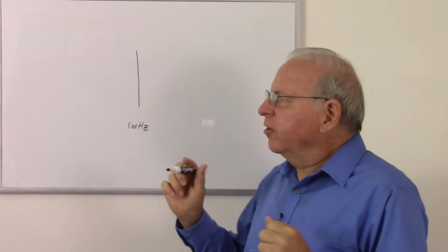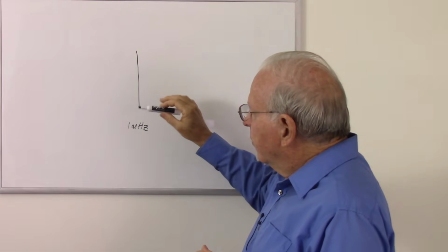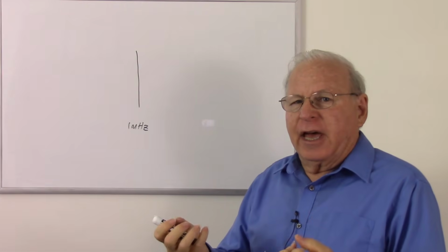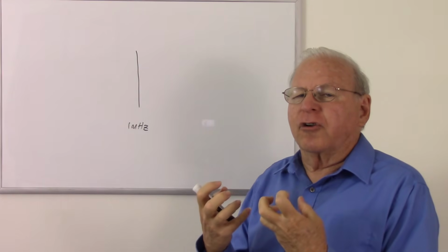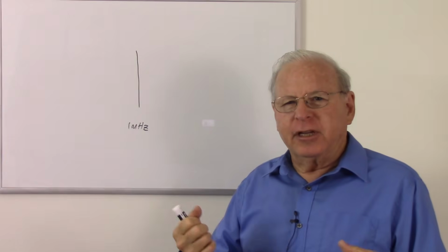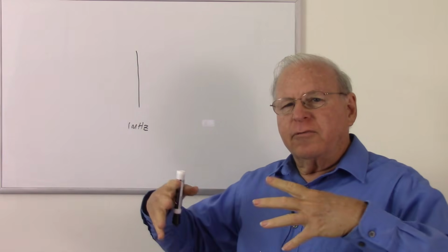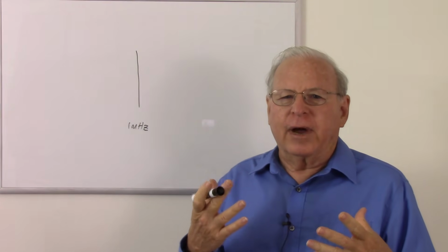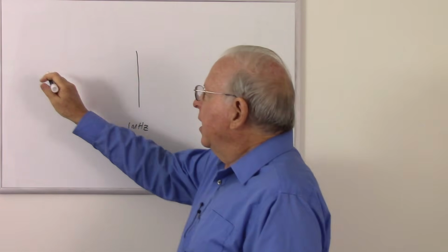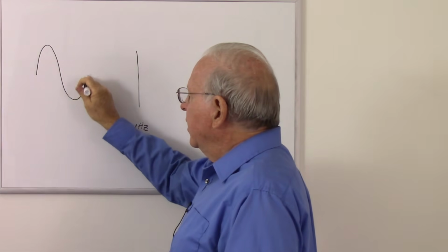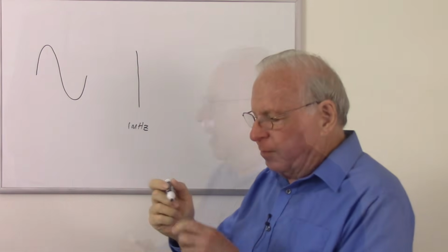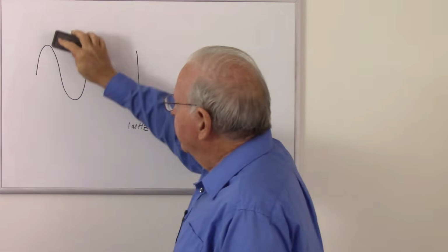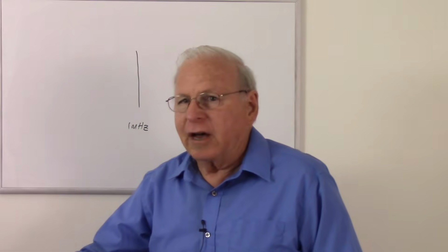And what I mean by that is, when we have this carrier, which is just a simple sine wave being sent to an antenna, and we have a current going up and down that antenna which disturbs the equilibrium of the space-time continuum and causes electromagnetic waves to radiate away from that antenna. And the power profile of those electromagnetic waves is a sine wave. So in other words, it goes up smoothly and down smoothly in power as time goes by. And we've already seen this shape in AC electronics, so we know all about what this sine wave means. So it's a pure frequency of 1 megahertz.